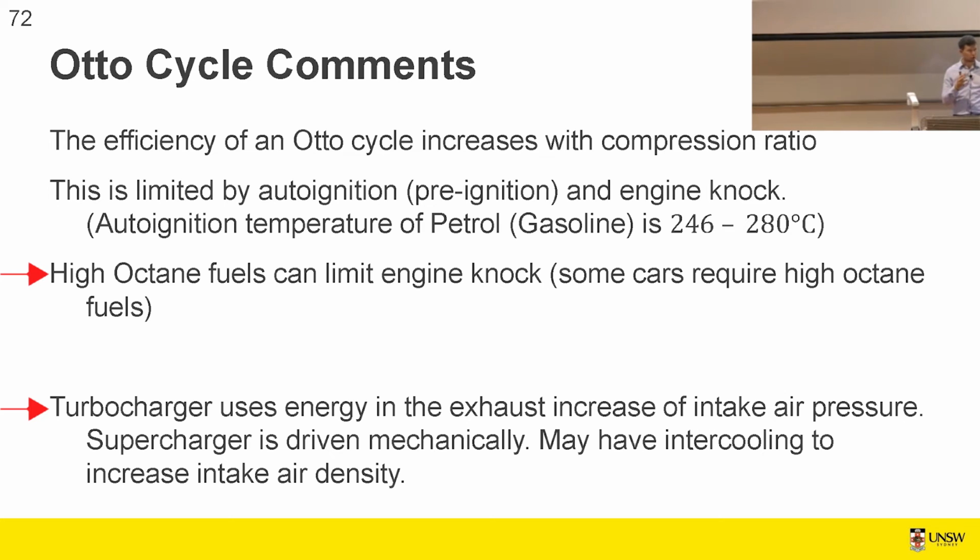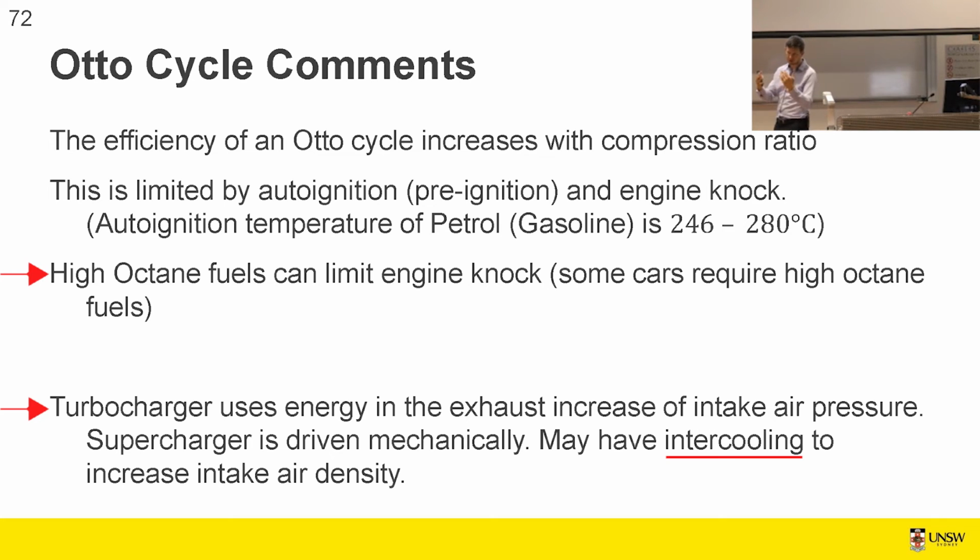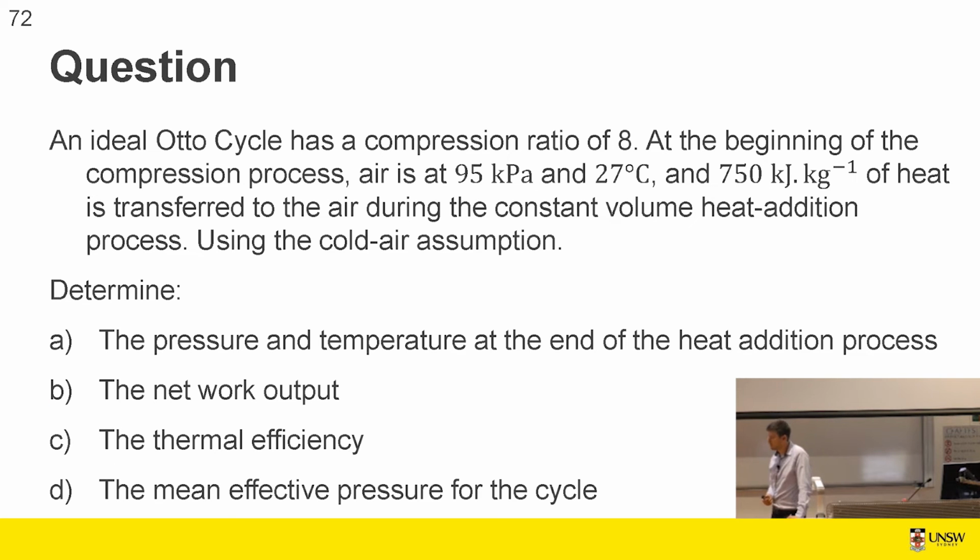The problem if you compress air on the way in is you also increase temperature. In the process of compressing the air, you raise the temperature because that's what happens. And so you might use an intercooler. And you might have two turbochargers separated by an intercooler. So the idea is you compress the air, then you cool it down, and so it's nice and dense when you go in. Then you've got a lot of mass of air, you can burn more mass of fuel in the same space. So let's look at this cycle.